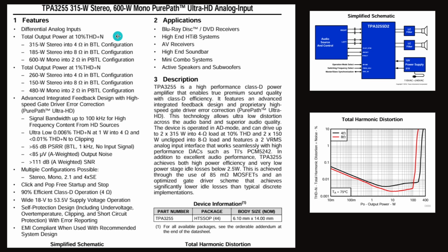First we have an active crossover filtering frequencies before the amplifier, and then we run the amplifier at clipping, and it generates tons of additional components. But for a woofer and subwoofer, our sensitivity to harmonics is low. At 10% total harmonic distortion, we feel nice, perfect bass. And that means this is the only scenario when we can use that power range that this particular chip can do.